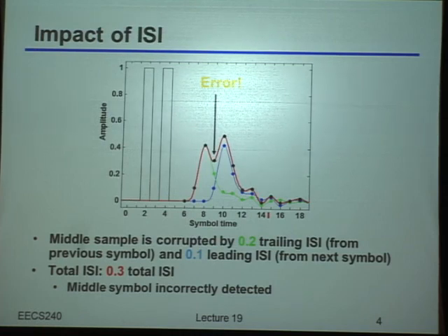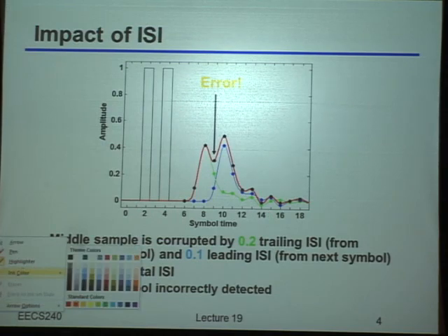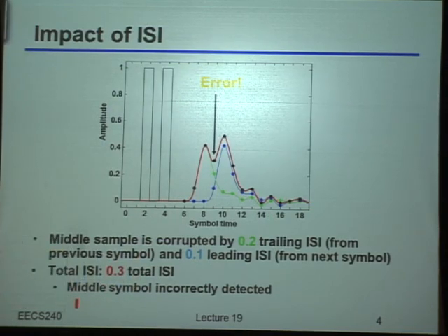Okay, it depends. What does it depend on? There we go. Okay, it depends on the threshold you choose. So take your pick. Where do you want to put the threshold? Say that again? 0.4. Okay, sure. Let's put it at 0.4. And let me get the right color here. Okay, so if you put it at 0.4, and ignore the fact that my lines are not very straight, what would you interpret it as at the receiver? Okay, you interpret it as 101.